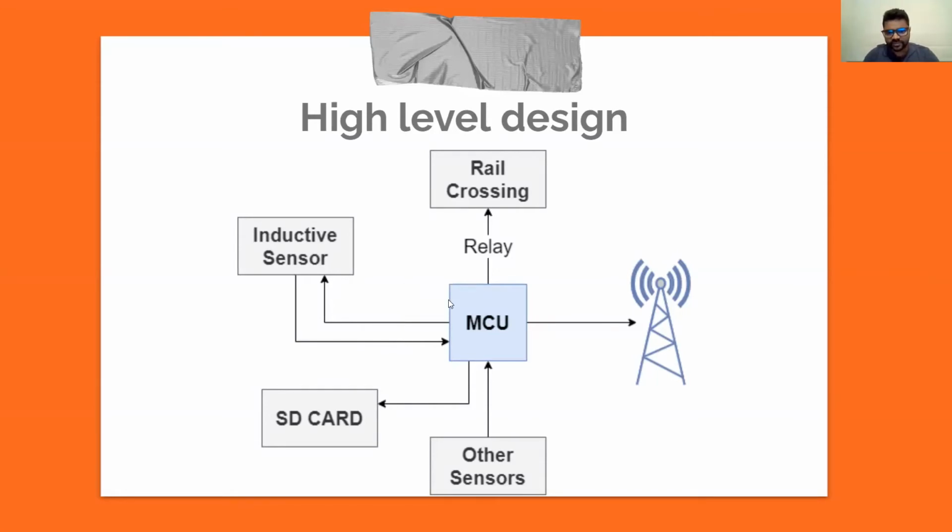But when it comes to safety related microcontrollers, they have something called a diagnostic period. Usually every couple of seconds, I can't exactly remember how many seconds, we have a diagnostic mode, which tests whether every peripheral is working. It injects a fault into our memory, and checks whether our memory detection units can pick that up.